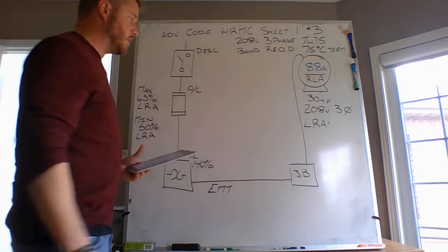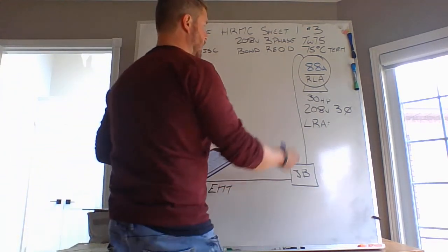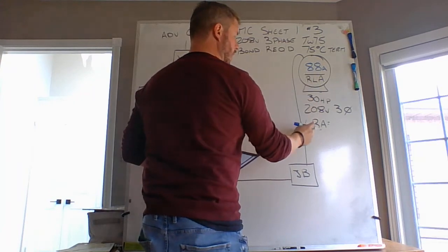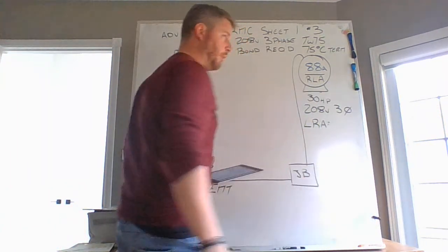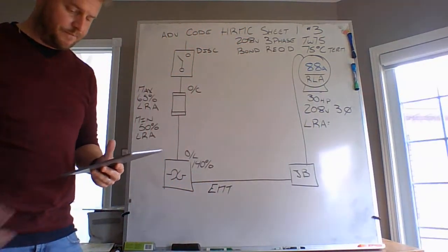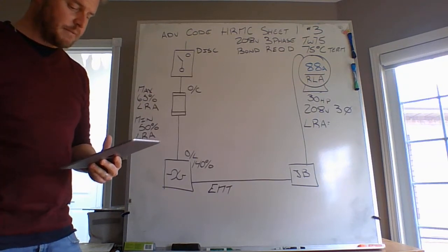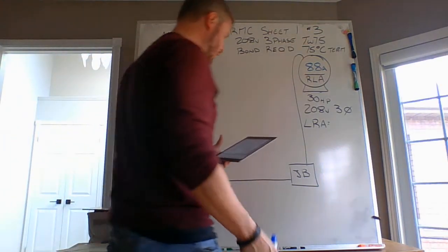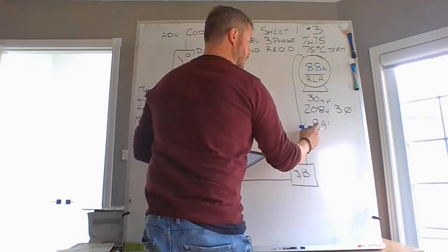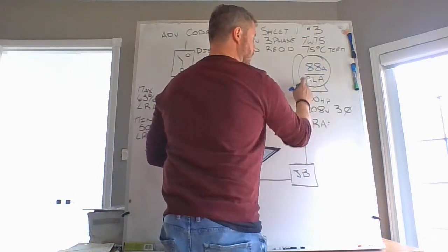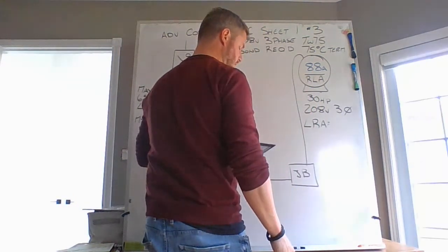Coming directly from section 28, the difference between your rated load current and your locked rotor current is a multiplier of 6. So step number 2 would be to look at your locked rotor current and calculate that based on your rated load current.